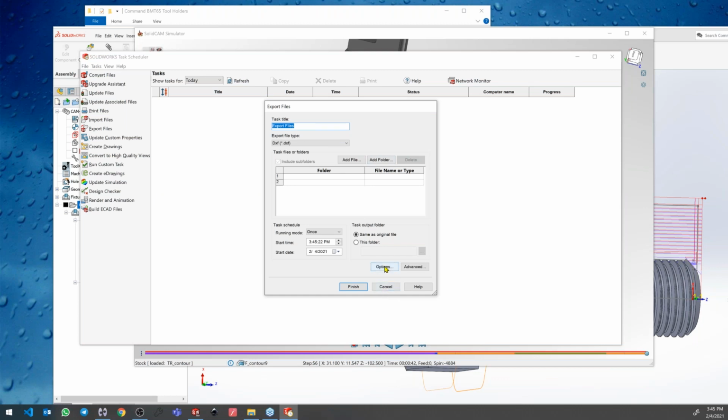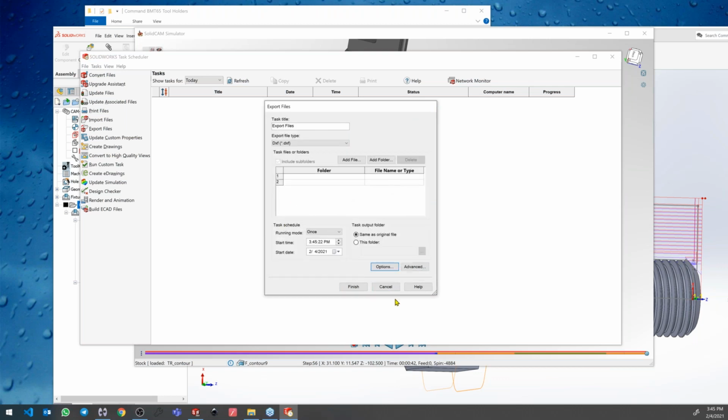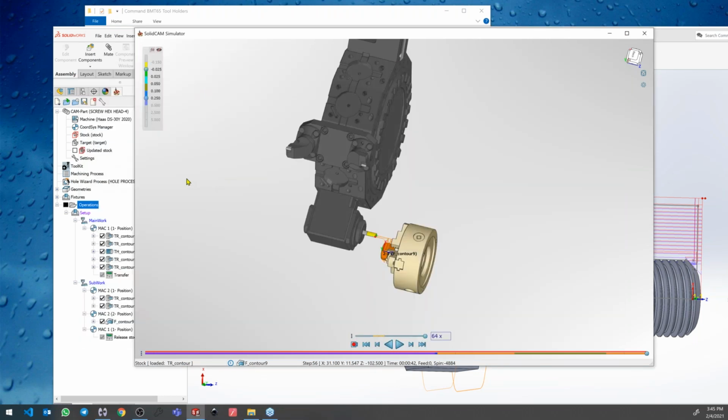Really easy. You can control parameters here and do everything you want. I really recommend playing with this tool. It can save a lot of time. You just download all your STEP tools to one folder or a few folder structures and make it by one click. Importing tools to the SolidCAM tool table also takes seconds, and once you save it, you can share it with other programmers, and you can play with it as you want.